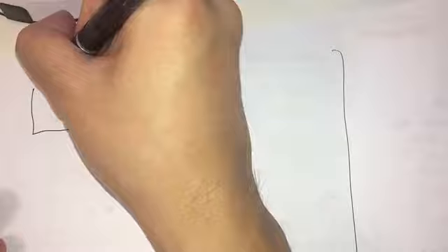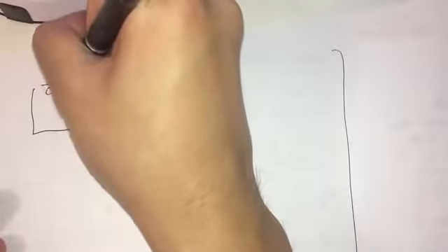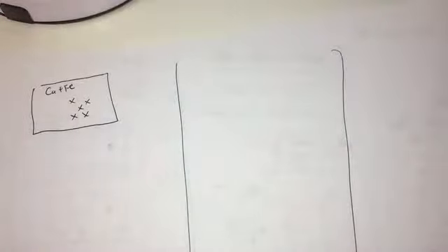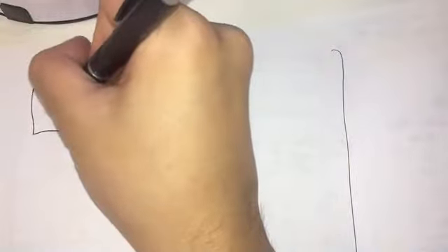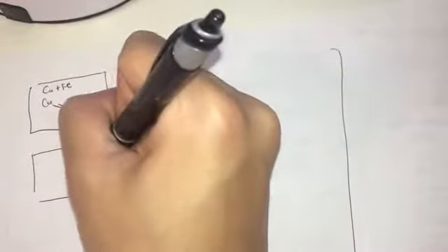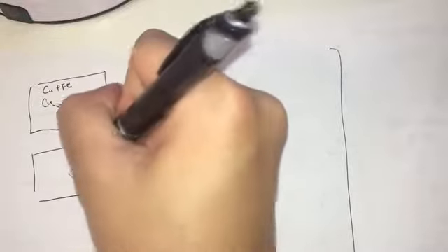So overall, if we have some even mixture of copper plus iron, and we have some vacancies scattered around here, I'll just use the X to denote vacancies, what happens is that the copper will tend to diffuse faster towards these vacancies, and they'll form their own copper precipitate.